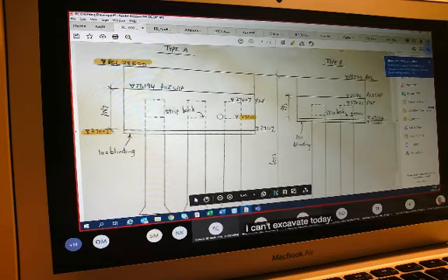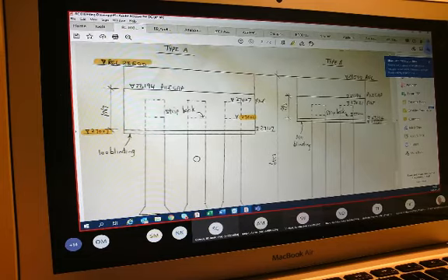But you see the 27203 is the top of my pile, and that is inside my pile cap. I cannot excavate to there. I have to excavate into the bottom of my blinding in order to ensure that everything gets in there, and that pile needs to sit partly into the pile cap.